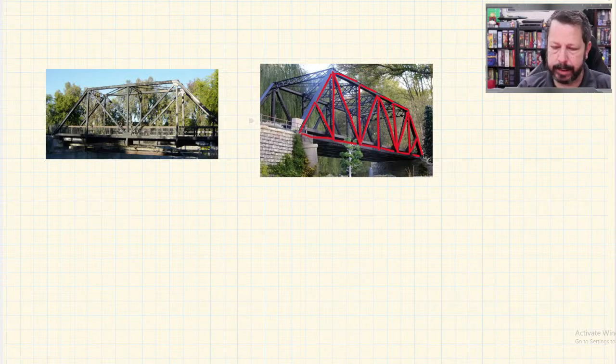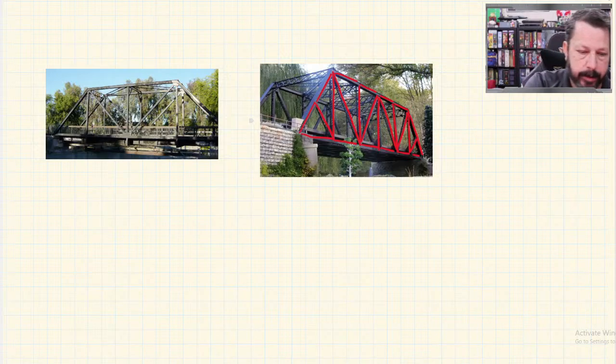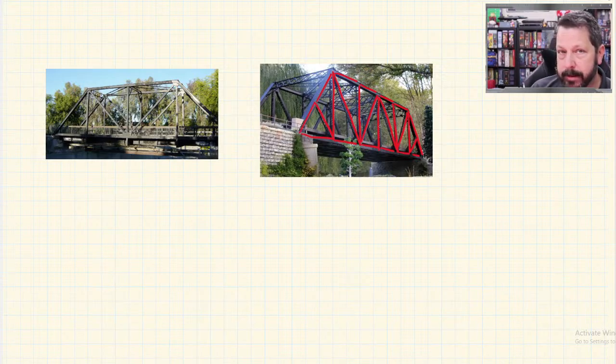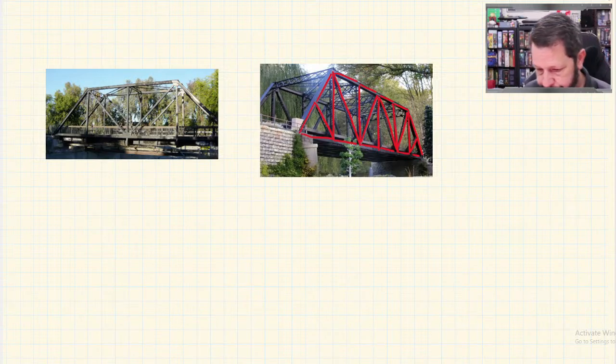All right, now that's all skewed. So let's redraw that head on so that we can actually do something with it and solve some of these things. I'm going to pick this one versus the other one just because there's more pieces to it, and it re-emphasizes why you might want to use method of sections instead of method of joints. On exams, homework, and quizzes, I don't specify that you use one or the other. I just give you a problem, and it's up to you to decide if you want to use method of joints or method of sections.